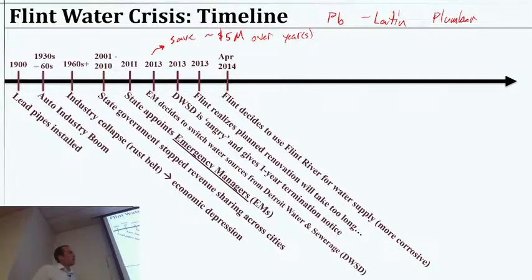And that's a questionable decision. Now, it would probably be okay if they properly handled it, but they didn't, which was the real big problem. Turns out the Flint River water is more corrosive. Maybe it's a bit lower pH. Maybe it simply just doesn't have the same buffers in it, not as much phosphate, which is a nice anti-corrosion chemical.